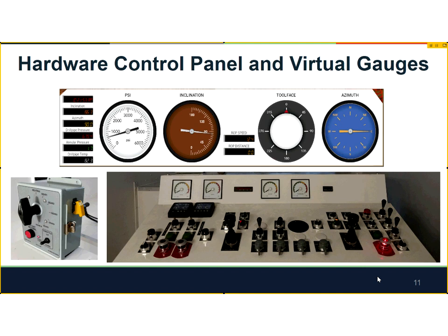And so we have a system of analog to digital converters. I talked about this already, but just for completion. So we pull wires from this system into the ADC converters. We're monitoring those at high rate, real time, and capturing the states of this entire system, putting it in shared memory that is basically being sampled by the uphole model every time it runs a cycle.